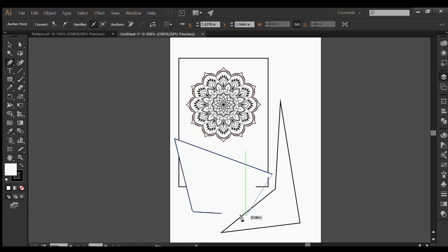Why that is the case, and what if you're trying to draw a complex shape and the fill is getting in the way, is that you could just click this, make sure that it's highlighted, and then click no fill, so that you'll only see the stroke.